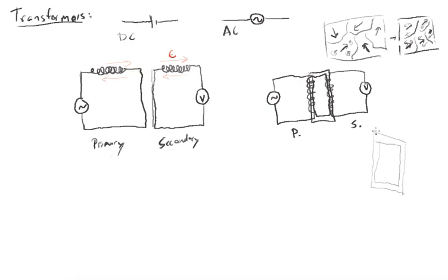And then on the back of it you put a thin sheet of something that's not conductive, like saran wrap or plastic or something. So you have an iron sheet, and then you have a non-conducting sheet, and then you have another iron sheet, and then a non-conducting sheet, and then an iron sheet, and you go back and forth alternating between this, and what you end up with is this iron laminate. You sandwich them together, you glue them together, and that's what a laminate is when you do something like that. You may have heard it with wood, like laminate wood, but it's a bunch of layers of iron and non-conductor, and you put them together, and then the laminate doesn't allow those little eddy currents to happen as much.